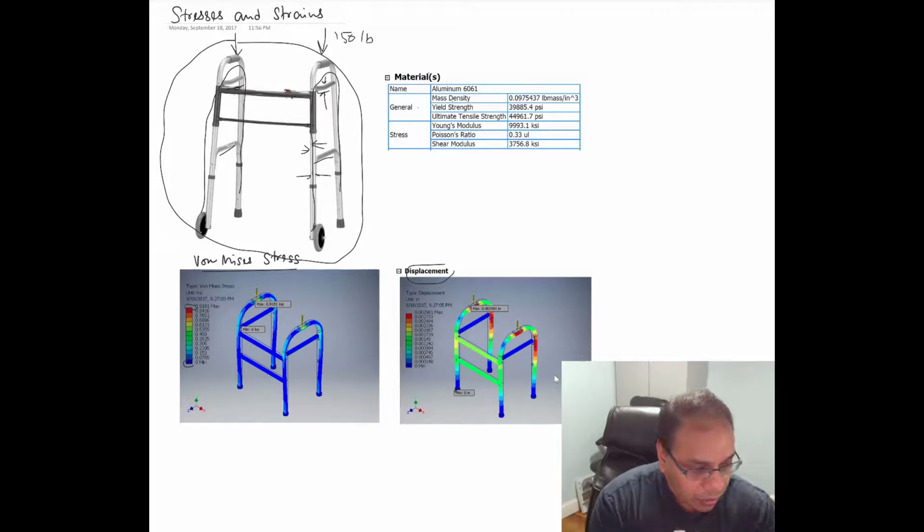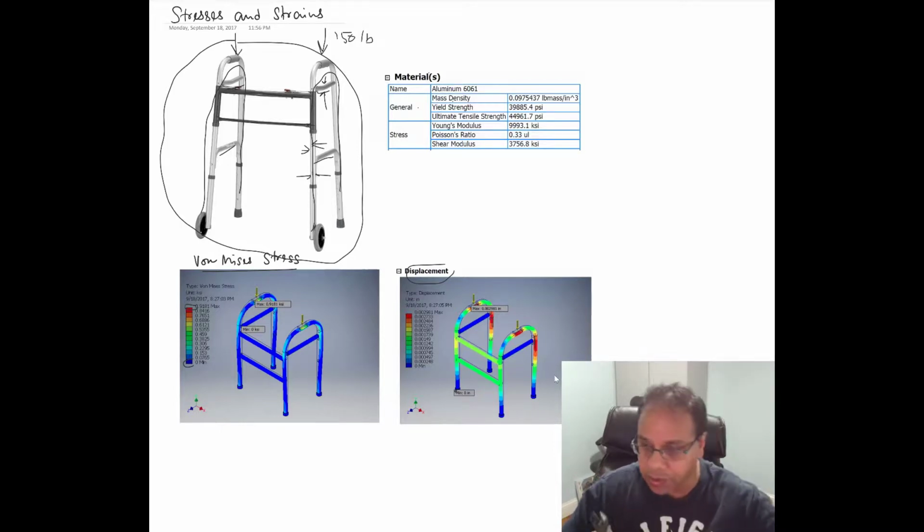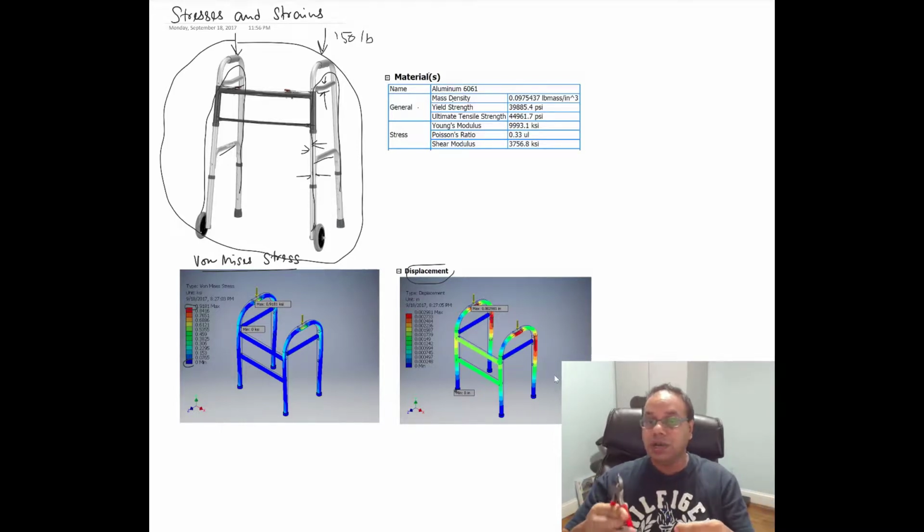On the other hand, you could also design products that you want to fail essentially. Okay, so for example, I have a wire shear over here. Now this wire shear is designed to cut wires, right? So when I apply a certain amount of load from this wire shear on the wire, I actually want this wire to fail, right? So we're designing for the failure. In this case, I want this wire to cut. This is my instrument that should cut this wire. So I have to know something about the material property of this wire and the kind of forces that I can potentially apply so that it would cut it.